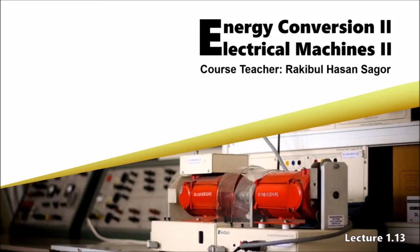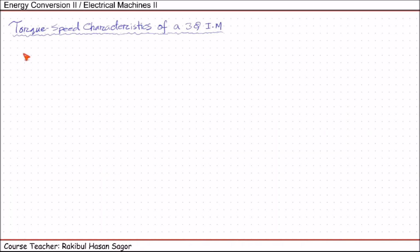Let us continue our class from torque speed characteristics curve. From our previous lecture, we saw the torque equation under running condition can be written as 3 over twice pi ns into slip s into E2 prime square into R2 divided by R2 square plus s into X2 prime square. Here, for a constant frequency supply, this 3 by twice pi ns is constant.